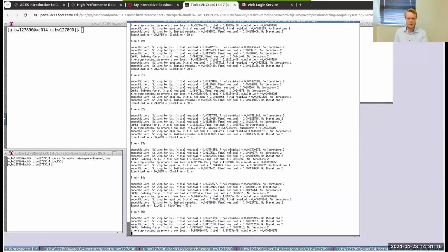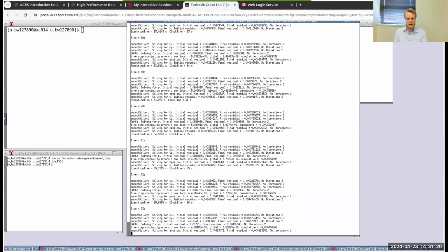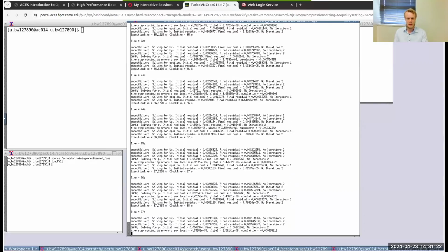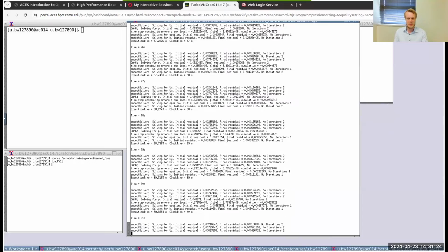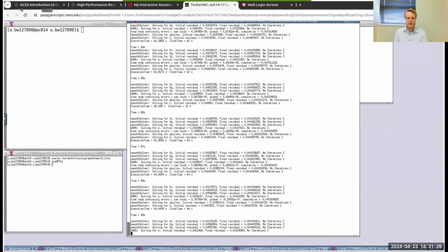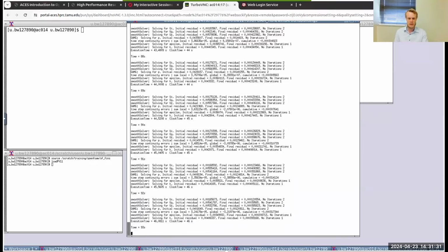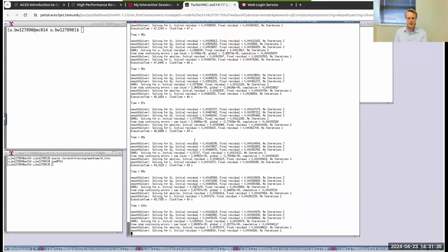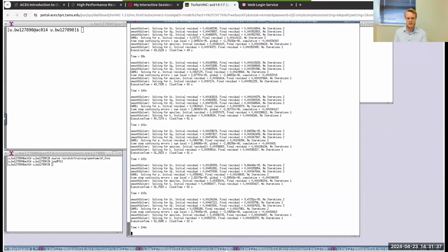But if you remember, in fvSolution there was also a residualControl dictionary with settings. If at some point the residuals go below 10 to the -4, it will stop automatically. If it doesn't, it will just continue to 400 seconds, which, spoiler alert, it will, because those residual controls were too strict for this case, I suppose.